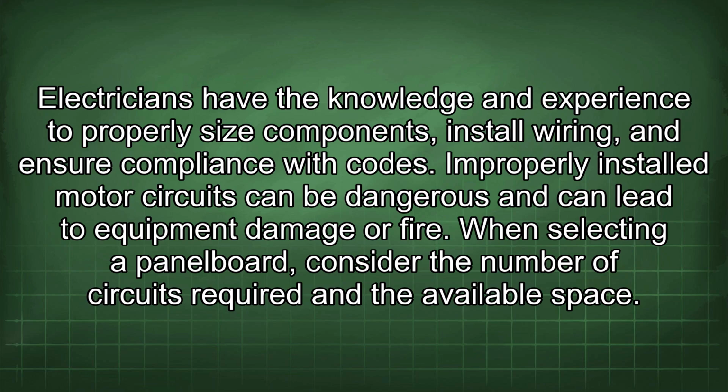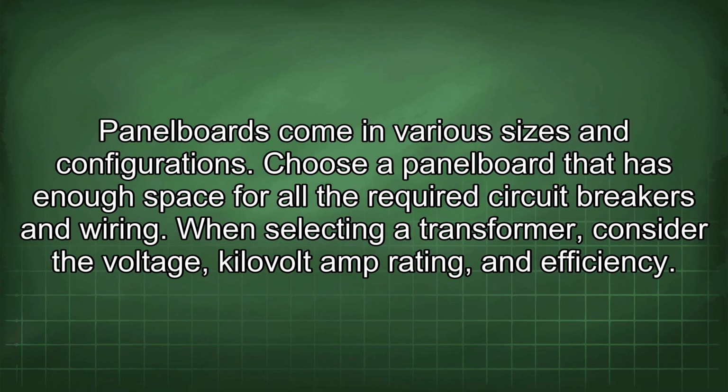When selecting a panel board, consider the number of circuits required and the available space. Panel boards come in various sizes and configurations. Choose a panel board that has enough space for all the required circuit breakers and wiring.